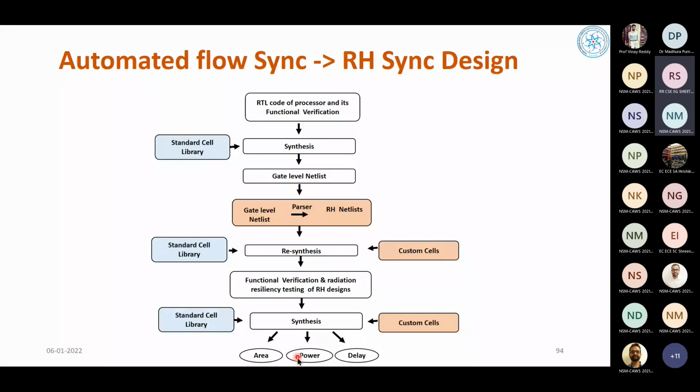Is it okay? And for area also, the standard cell library has another file called the LEF file, layout exchange format. This file contains the area for every gate. Suppose I have an AND gate, how much area is it going to take? If you have a cell count of, let's say, all NAND gates, then you can say this is the total area that NAND gates will take. DC does this for us, so we don't have to calculate the area, but we always give a small circuit as an example and then we test it.